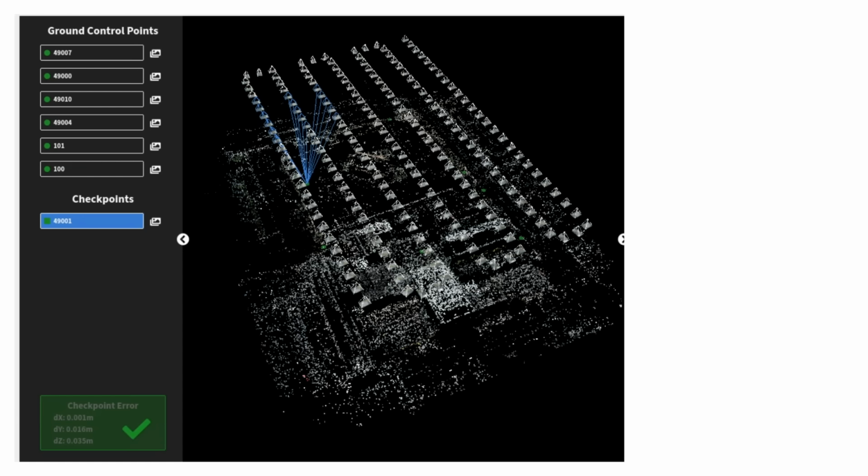because essentially, like I said, with RTK capable drones, these are sky control points. Okay, so you've got a bunch of control points in the sky, you've got control points on the ground, you've got checkpoints. They're all using the same carrier phase measurements. They're all using the same type of observation. So they should have similar accuracy.